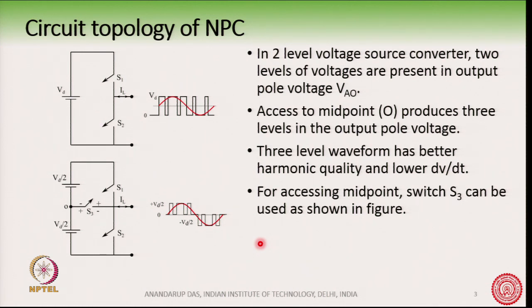The benefit, as compared to the earlier waveform, is that the instantaneous error is less in this waveform. Here, on the positive side, sometimes we were using a pulse which was far away from the red waveform, and here we are using a pulse which is closer to the red waveform.